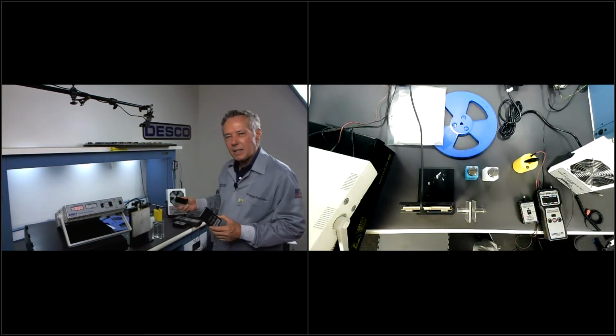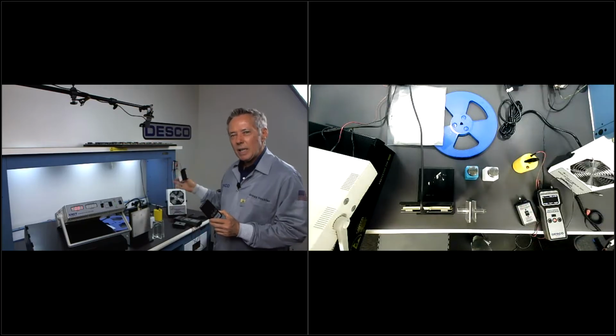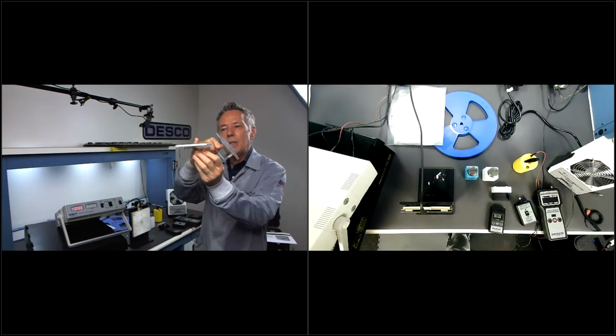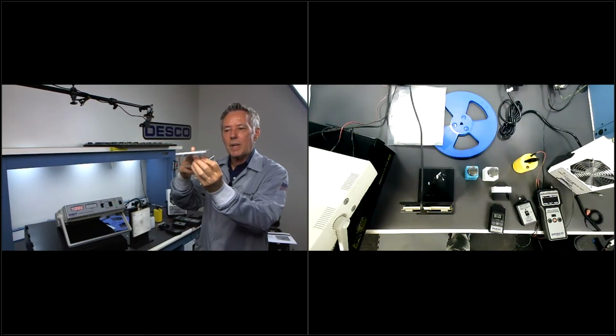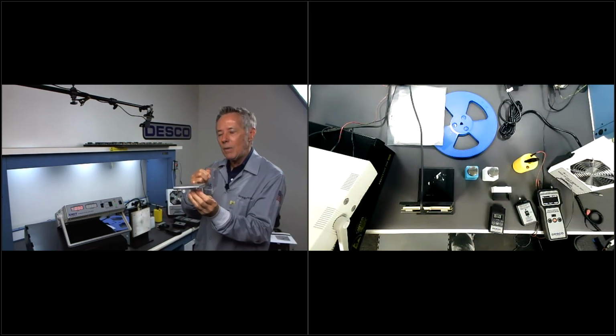I also have what's called an ionization test kit. When you combine this hood with my static field meter and a charge generator to put voltage on this hood, now I can use this equipment to test my ionization. I have these paddles that Desco has developed, a solid piece of acrylic and a solid piece of aluminum on a piece of acrylic. So this represents that plastic bag, that cell phone case. This one represents an uncharged conductor, you not wearing your wrist strap, or an IC sitting upside down on your ESD mat and the leads aren't touching that IC. Any conductor that's not grounded, all right?